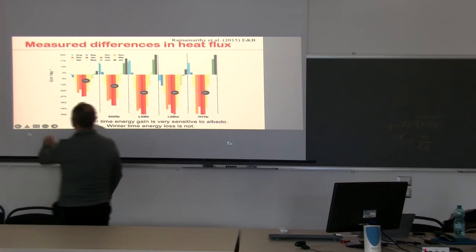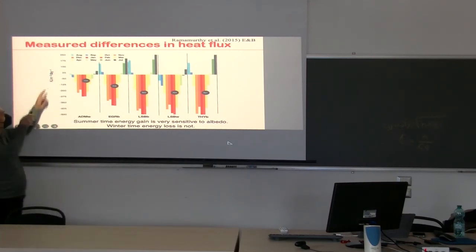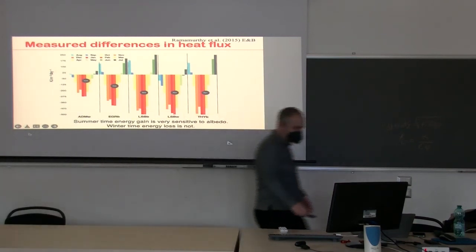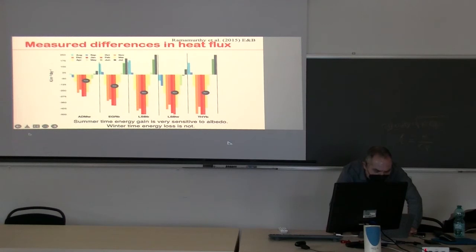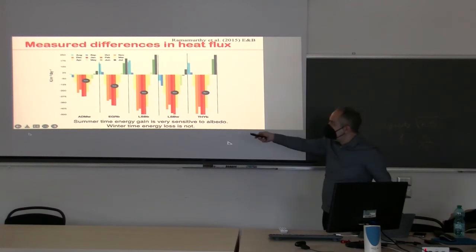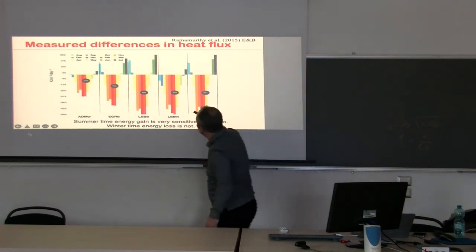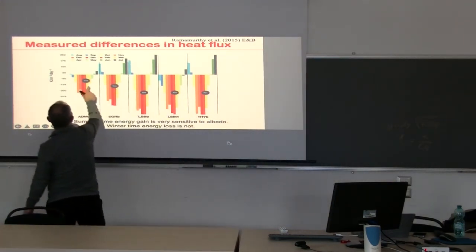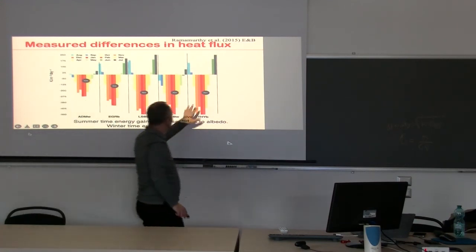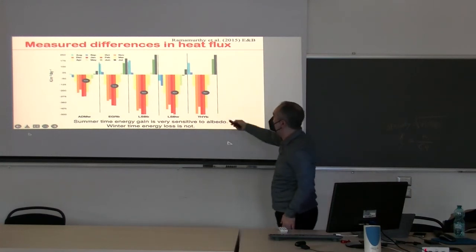So this is how much energy is flowing, per square meter per day, into the different roofs. This is a white roof, W at the end, but their R values are changing. Okay, sorry, this is really not legible here. But let me tell you that this is R12, and then this is R31. So this is the insulation, right? So this is R12, this is R30. So these are much more insulated than this one, okay? Sorry, the other way around. This is the least insulated, and that's the most insulated, obviously.